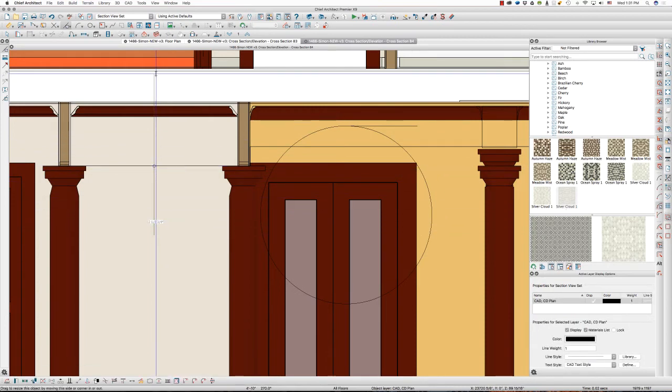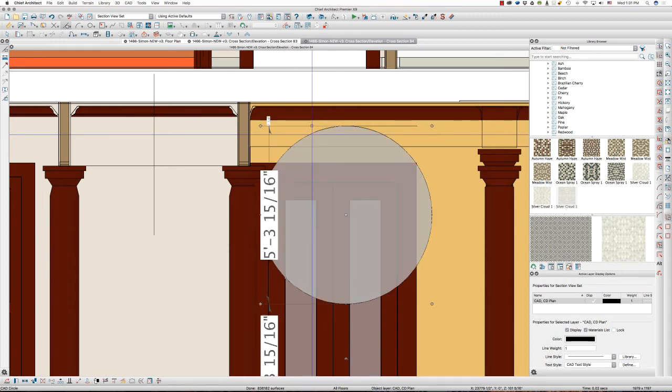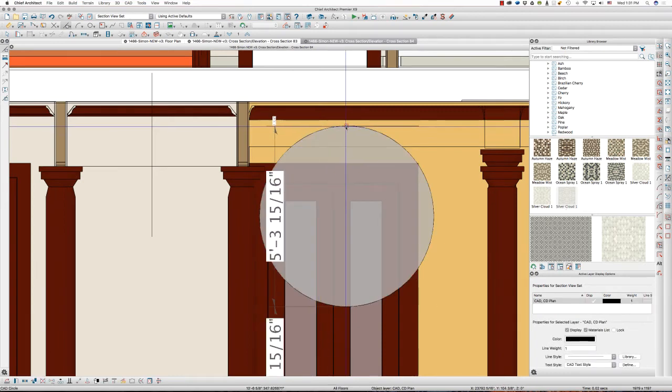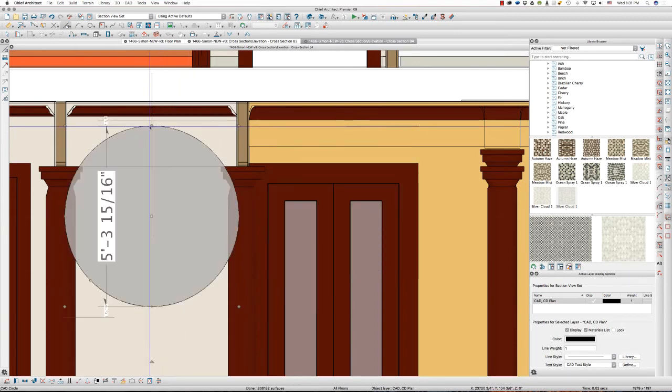That's fine. I'm going to pull up that construction line. Now I don't care about this construction line so much that we copied over, so I'm just going to select my circle and Command G to try to center it. Command G isn't working, so I'm going to cancel that, select my circle again, and hit X on my keyboard, the point-to-point move. So I'm going to take the top quadrant of the circle and move it onto the space here.